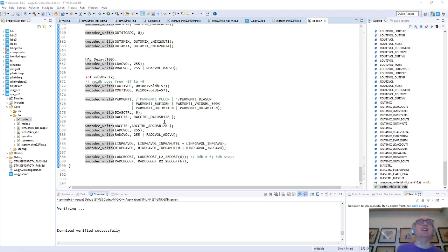I've actually had NACKs and intermittent failures on the Plinky board that had pull-ups and used the proper library. One time in 10, it wouldn't boot properly, and I had to put retries in. With my bitbang, I've never had it go wrong. In fact, it just worked without me even configuring the pins, which is hilarious. So blah, blah, blah. I think I better stop.